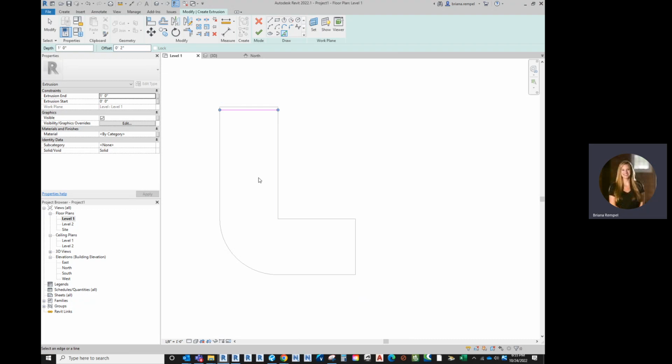If I click here, it's going to do that offset from the line that I'm picking. But I can even do this one step more efficiently. If I just hover and tab, that's just 2 tabs. So I hover, hit tab once, tab again, just tapping it like space bar, not holding it down. And I'm going to get this chain of walls or lines, and just click once, and there you go.